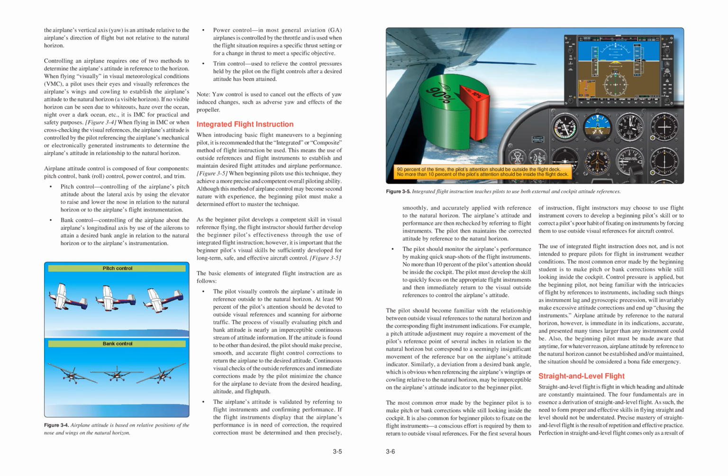The most common error made by the beginning student is to make pitch or bank corrections while still looking inside the cockpit. Control pressure is applied, but the beginning pilot, not being familiar with the intricacies of flight by reference to instruments, including such things as instrument lag and gyroscopic precession, will invariably make excessive attitude corrections and end up chasing the instruments. Airplane attitude by reference to the natural horizon, however, is immediate in its indications, accurate, and presented many times larger than any instrument could be.